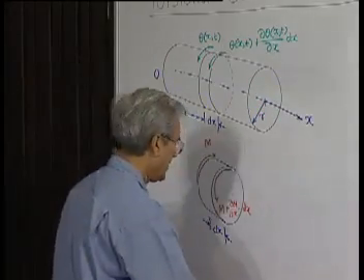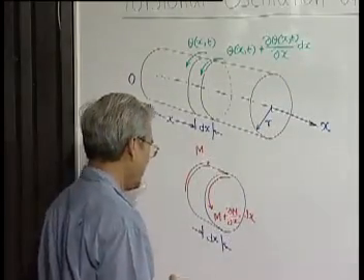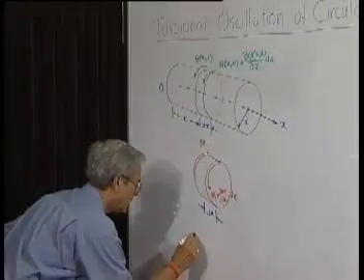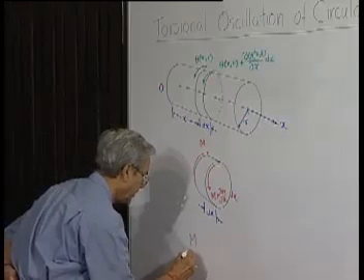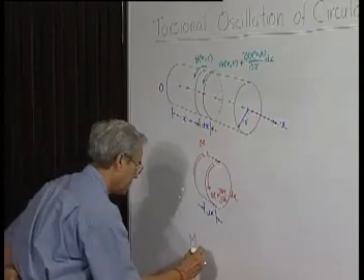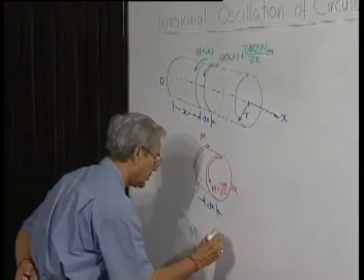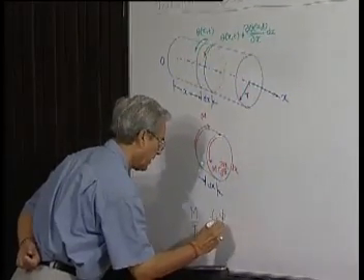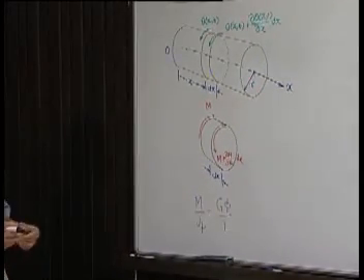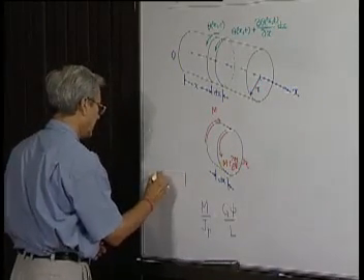Then the twist which this shaft is subjected to, it may be an element but nevertheless it is a shaft, will satisfy our standard relation: moment on a shaft divided by the polar second moment of area is equal to shear modulus G times the amount of twist phi divided by the length L. This is the standard relation we know for the torsion of a shaft, whose length is L.